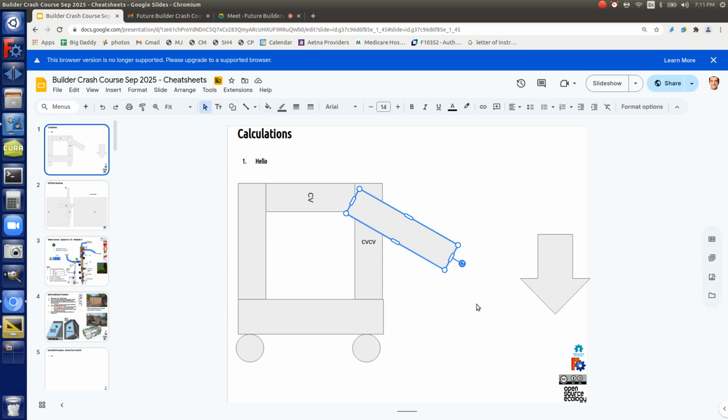Well, typically people use bushings, because if you're going only against the quarter-inch wall of that steel, it'll just start egging it out over time. Now 7,000 pounds, that's the weight, but impact loads are what you're going to have to consider. So we calculate from first principles. Okay, we can hold like 200,000 pounds, but what if you just ram that tractor at full speed into a brick wall or a tree? What's going to happen? Well, we just calculated in theory that 4-inch tubing gets you about 200,000 nominal pounds of strength.